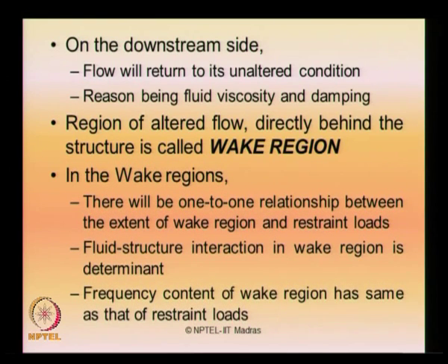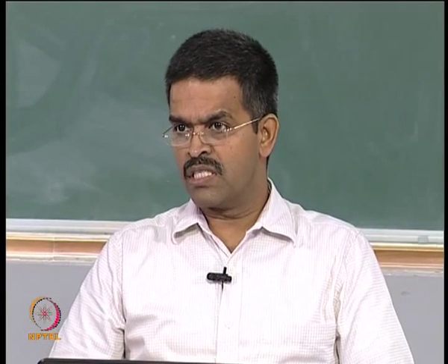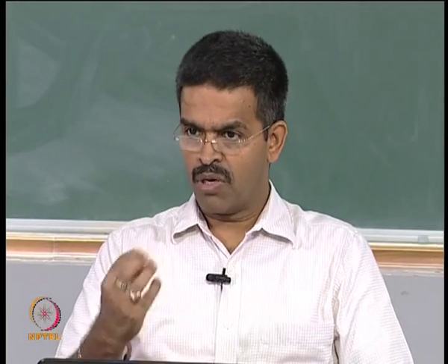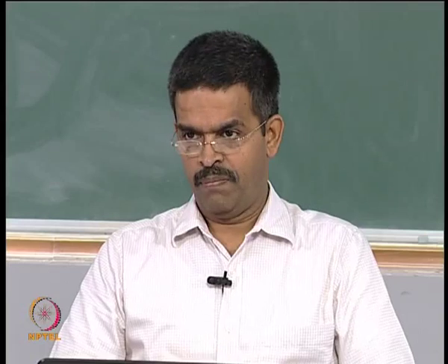Now, in wake regions there are many important things happening. There will be a one-to-one relationship between the extent of the wake region and the restraint loads. What do you understand by restraint loads? Restraint loads are loads generated either from the complexity of the geometry of the structure, for example floating or fixed, or because of the boundary conditions established by the structure with respect to the seabed, whether it is bottom supported or freely floating.